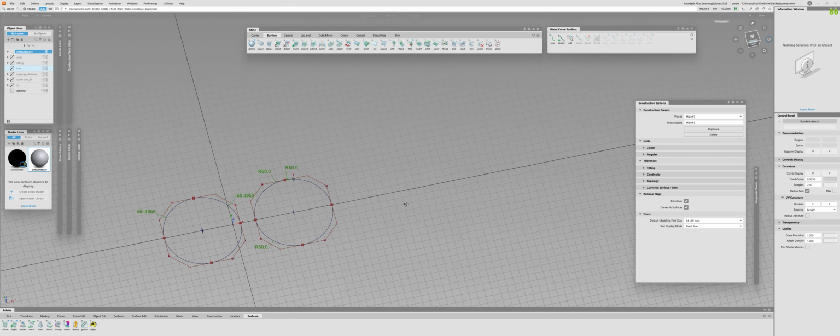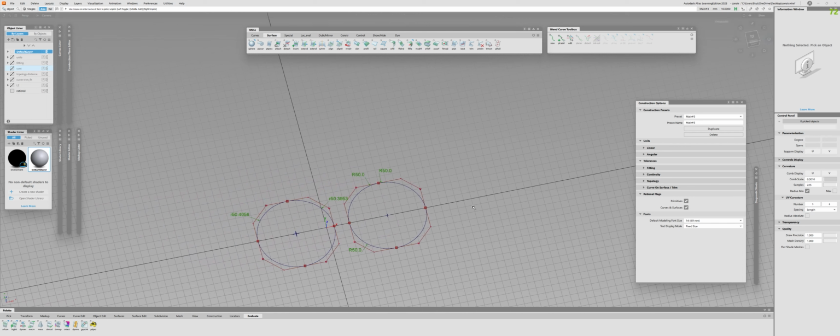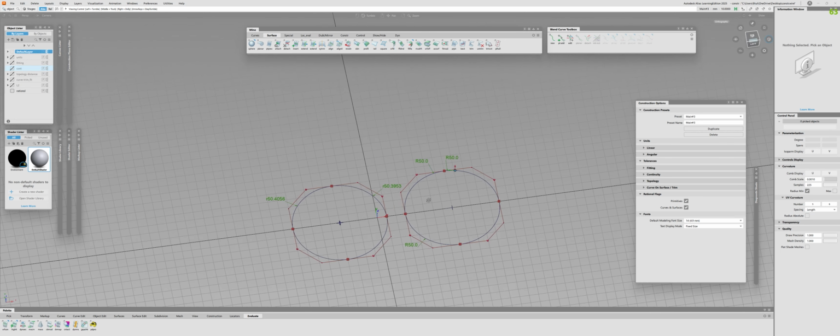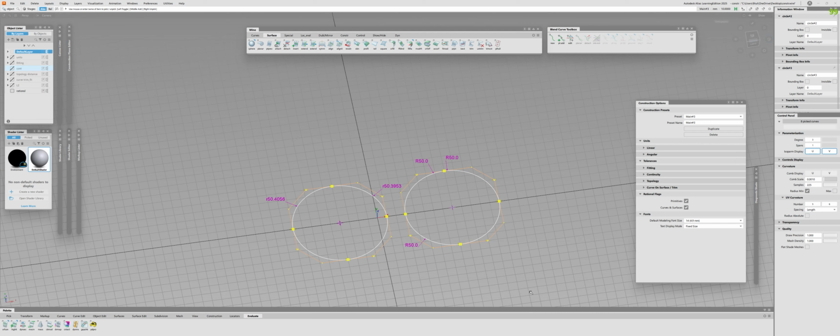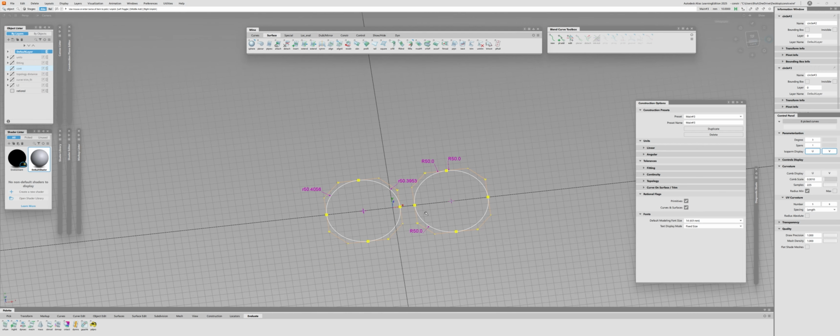Once again, all of this rational flag stuff affects only circular shapes. It's designed to create perfect circles and perfect circular surfaces, revolves and sweeps from them. It doesn't affect anything else. And it's really tied to the different types of circles. I just really briefly touched it here. But the next video will be specifically about the circles and about the rational flags, so stay tuned. Okay, so that was about the rational flags.